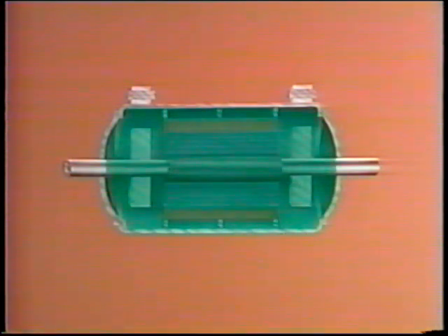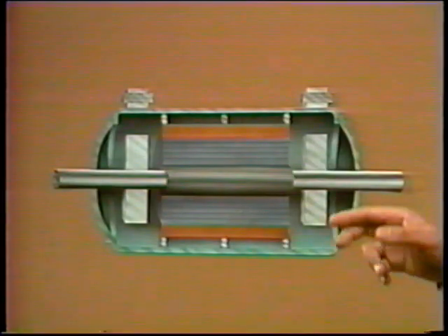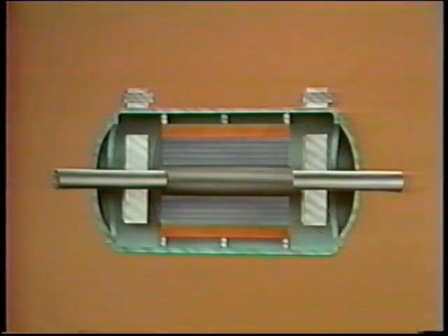The generator's filled with hydrogen, which circulates around the inside. Hydrogen circulates through the rotor and stator windings, continually picking up heat produced by the generator. Then, the hydrogen flows through heat exchangers, where the heat's removed and then flows back to the windings. The hydrogen never leaves the generator. It follows a closed flow path. But the heat does leave the generator. Water flows through tubes in the heat exchangers. In the process, it picks up heat from the hydrogen and carries that heat out of the generator.